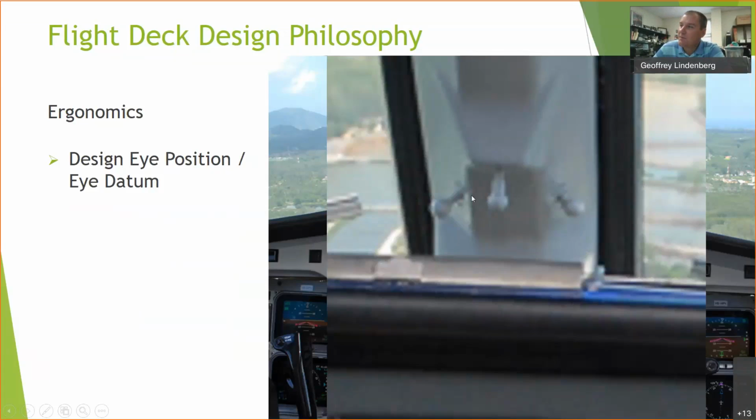Okay, you'll be looking from an angle over here, and this should be right behind it if you adjust your seat correctly. Consequently, if you're sitting in the right seat, you're looking at this front ball right here. This ball off to the left should be directly behind it. So when you get into a flight deck, if you're trying to figure out if you have your seat adjusted correctly, you can use the eye position indicator to figure that out.